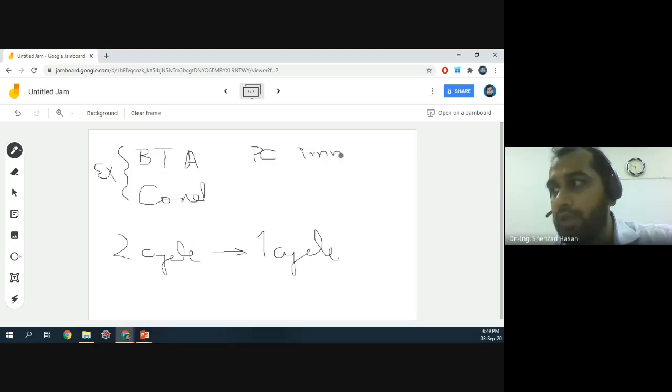Because you need to add them to calculate this branch target address. The program counter value would be available in the first cycle, because the program counter is the main thing from which you have fetched the branch instruction. So you have this value in the first cycle, but you don't have this immediate value in the first cycle because that is going to come from the instruction.